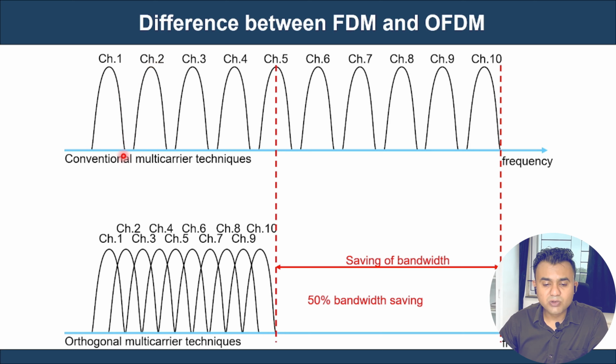Now this is to avoid the interference. But we did not use the orthogonal frequencies. That means we need the guard band to overcome the interference. However, you can see because of this, there is a wastage of the bandwidth. We are not using our bandwidth optimally.